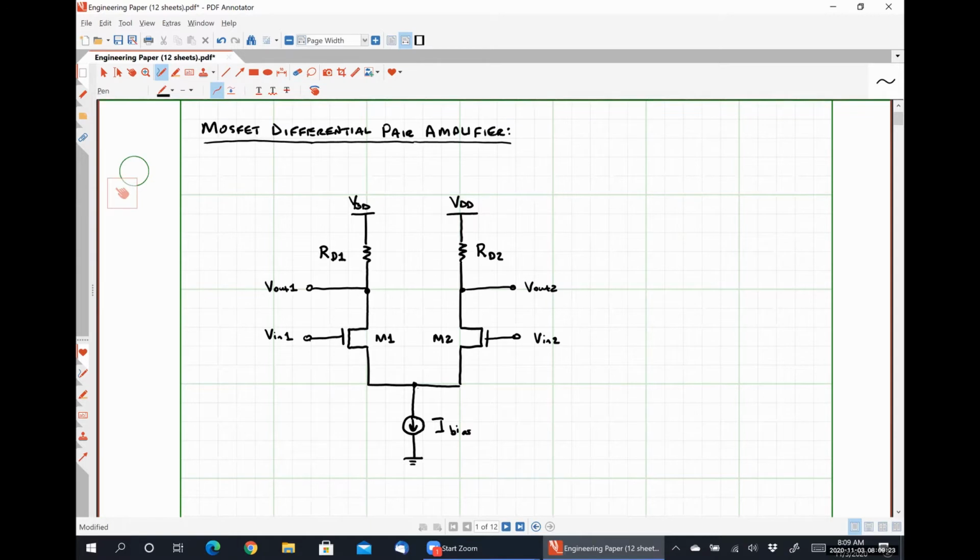This circuit is one that requires balance for proper operation, so it's very critical that the resistors and the MOSFETs are matched, meaning that they're of the same size and things like that. So if we were to look at this as a DC circuit where we're making a couple of simple alterations, let's say, for the sake of argument, that I grounded both of my input terminals.